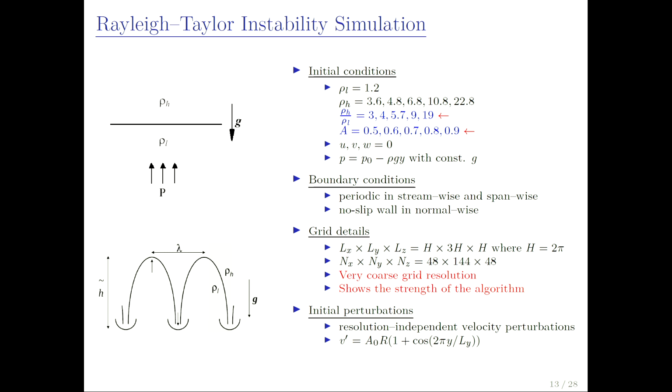By making it linear, you're putting in two problems at once. Number one, you don't start with a steady state solution plus perturbation. You start with a solution which is not steady, so your interface will develop until you develop the exponential profile. So you're mixing two problems together. I think you need to change the initial conditions. Because if you solve the steady state equation, it's not linear. It is exponential, because you have to solve dP/dz equals rho g.